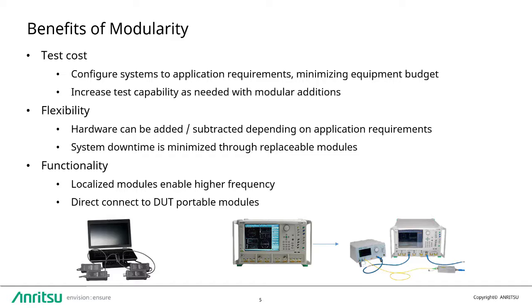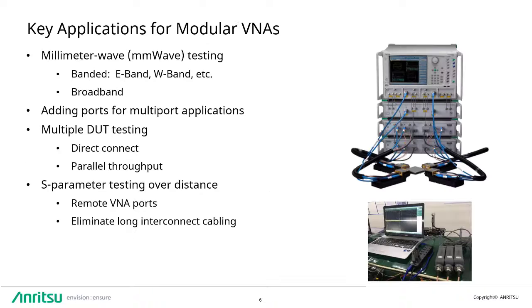Modular systems supporting small, independent measurement modules, such as one-port VNAs, enable direct connection to the DUT, improving dynamic range and measurement stability by eliminating interface cables.